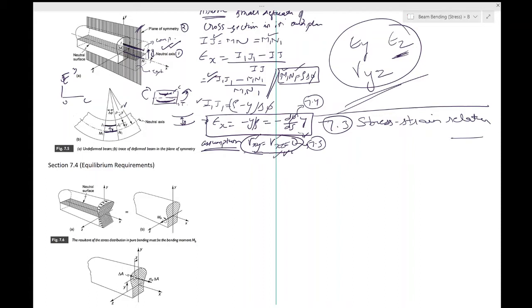Okay, so if the material properties do not change along the length of the beam, then these properties are also symmetrical with respect to the xy plane, and hence within these limitations the material can be non-isotropic, linear or non-linear, elastic or plastic. Okay, so in reality you can have any sort of a material, but we will restrict our discussions to always linear, elastic, isotropic material. Okay, because we are just beginning into this solid mechanics right now.